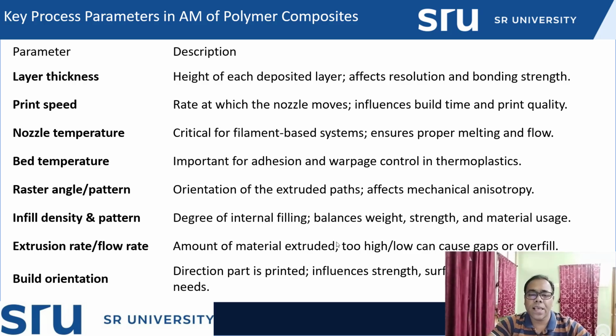Similarly, the raster angle and the print pattern will be there. The raster angle will also decide the orientation of the extruded path. Similarly, it will affect the mechanical properties, the anisotropic properties of the materials. So this also is a very, very important parameter.